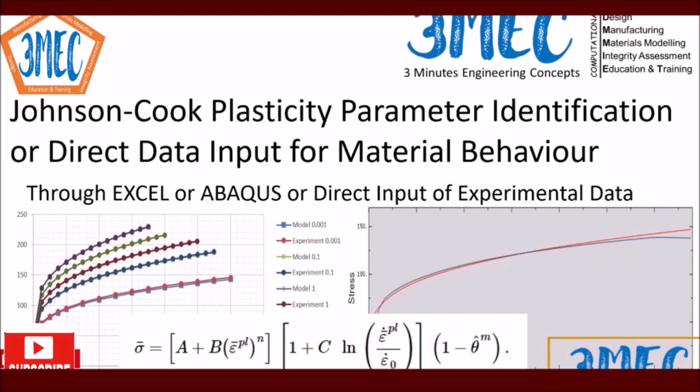In this video I will explain how to identify material parameters for the Johnson & Cook plasticity model, and I'm going to show you two ways of doing it. One is using Excel, because it's generally a uniaxial case, so you can survive with Excel as well. It's a one-dimensional problem in reality. And also how you can do it in Abaqus, which is a more tedious way of doing it unless you know Python.